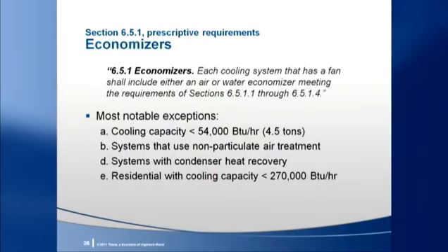Next, let's discuss the implications of the requirement for an economizer. As part of the prescriptive requirements, ASHRAE 90.1 requires that each cooling system that has a fan shall include either an air or water economizer. There are a number of exceptions.